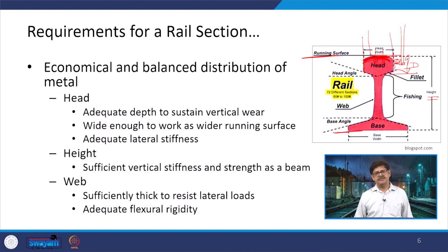This height is another point which needs to be taken care of. The whole system is being designed as a beam, and when it is a beam, we are looking at the stiffness and the strength of that beam with respect to the vertical loads, and with respect to the moments which are going to be induced in it because of the hitting by the flanges and the pressure which is going to be there at the bottom.